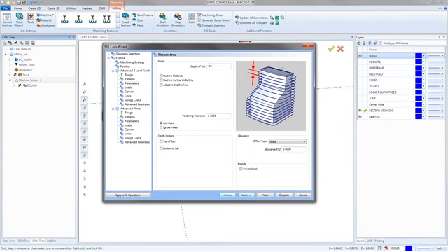I have no clue how many hours and how much time I've wasted putting a toolpath in and going, okay, this one's got to be a real fine finish, so I'll put it at 10 thousandths. I wait for it to compute, and then I watch the simulation and realize the toolpath I picked was not even close to the right toolpath. My thought process wasn't even right. So what I do is I go back and start modifying. And sitting through all those calculations, you kind of figure out, hey, if I'm just trying to figure out which one's going to work, leave the depth of cut a little heavier. It'll calculate faster. Yeah, make it a heavier depth of cut.